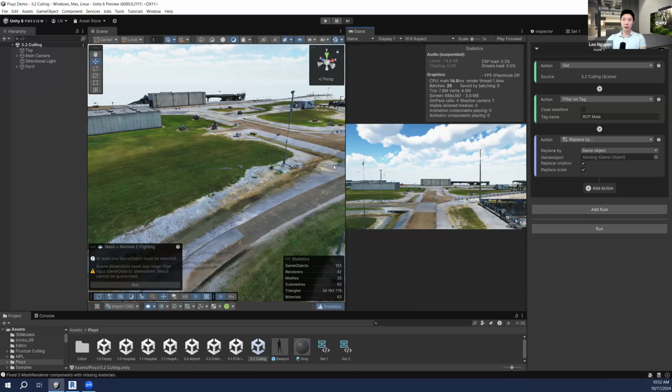So that's usually my rule of thumb: for anything that I'm able to run on my PC, I would probably have to optimize it with a 50% reduction or more in either the number of game objects or triangles if I'm wanting to also view it on a standalone device like the Quest. There's also a medium option, where you are streaming the content directly to a Quest, and you're still leveraging the GPU on your main PC.